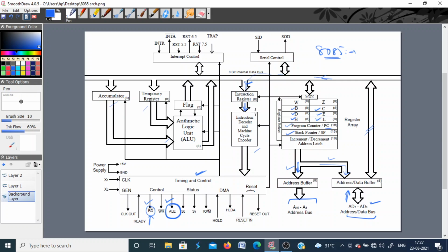Okay, this is what we have discussed. We have a register A, the accumulator, which is an 8-bit register, and it is part of the ALU. That is why it is separate from these. All the arithmetic and logic operations are performed with A as one operand. So one operand to the ALU is fixed. The second operand can come from anywhere.